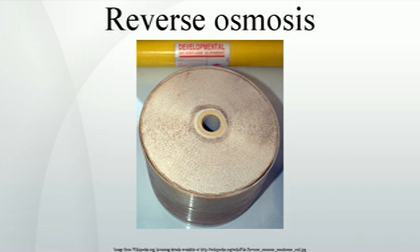Formally, reverse osmosis is the process of forcing a solvent from a region of high solute concentration through a semi-permeable membrane to a region of low solute concentration by applying a pressure in excess of the osmotic pressure. The largest and most important application of reverse osmosis is the separation of pure water from seawater and brackish waters. Seawater or brackish water is pressurized against one surface of the membrane, causing transport of salt-depleted water across the membrane and emergence of potable drinking water from the low-pressure side.